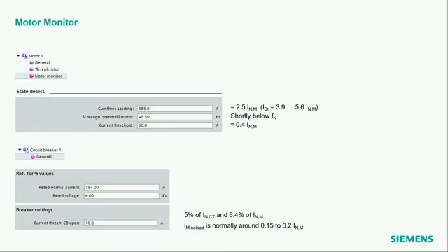So we get K-factors around 1.1, 1.15 maybe for motors. So I have enough space to that, 3.9 to 1.2. So I take something in the middle, 2.5. This should be fine because here I'm far away from any overload situation of the motor as such.